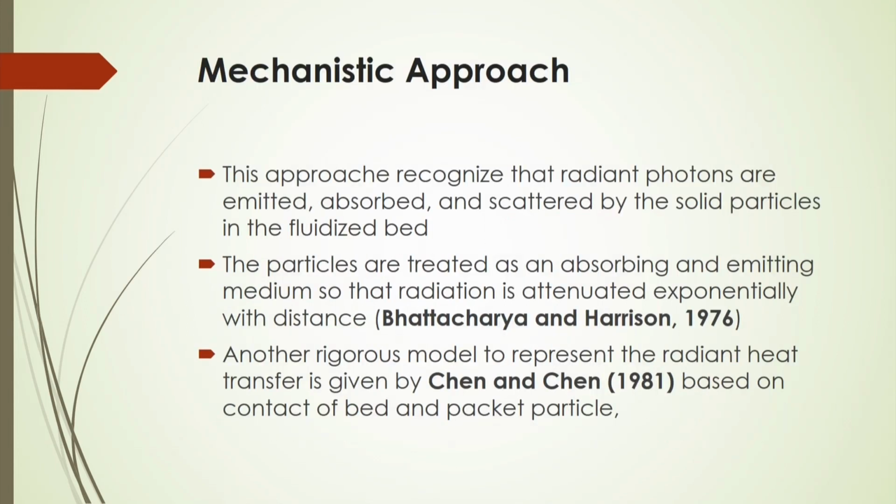Whereas the mechanistic approach recognizes that the radiant photons will be emitted, absorbed and scattered by the solid particles in the fluidized bed. The particles are treated as an absorbing or emitting medium, so that the radiation is attenuated exponentially with the distance.